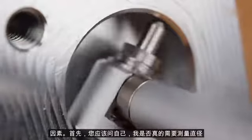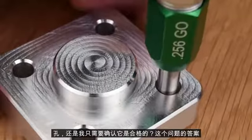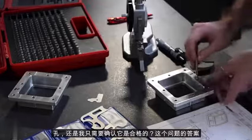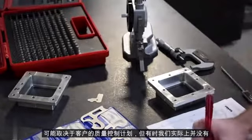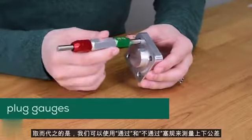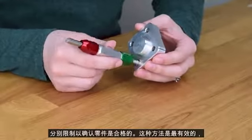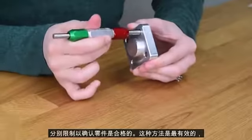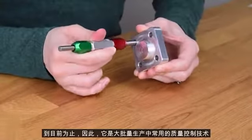For one, you should ask yourself, do I actually need to measure the diameter of the hole, or do I just need to confirm that it is in spec? The answer to this question may depend on a customer's quality control plan, but oftentimes we don't actually need to measure a hole directly. Instead, we can use go and no-go plug gauges for the lower and upper tolerance limits, respectively, to confirm that a part is in spec. This approach is most efficient by far, and for that reason, it is a common quality control technique in high-volume production work.